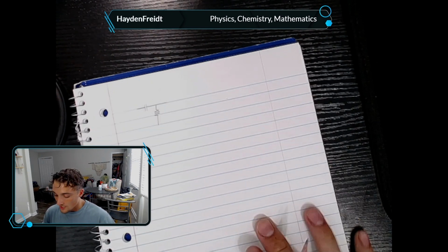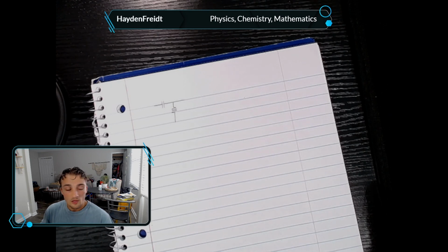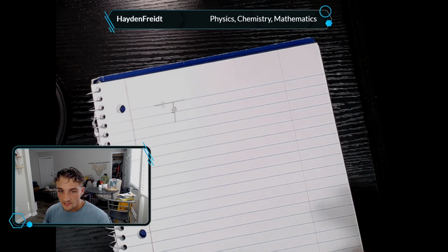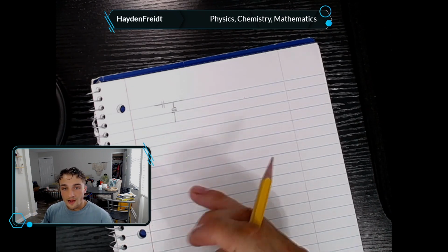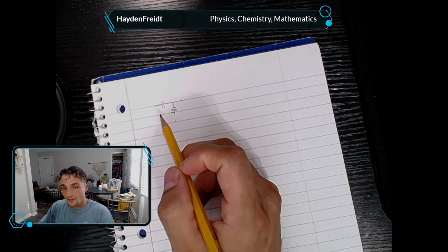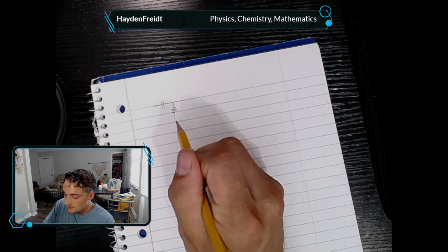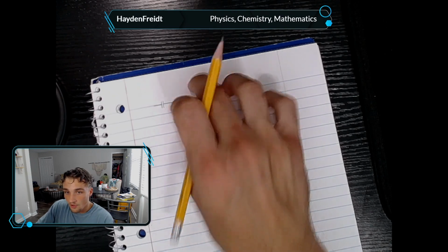The capacitor itself acts differently in a transient analysis compared to a frequency analysis. Right now we're about to do a frequency analysis, meaning our input is some cosine or sine wave that has a particular amplitude and a particular frequency. It's a very basic fundamental filter: our high pass filter, with the capacitor in series with the resistor, but we take the output across the resistor.